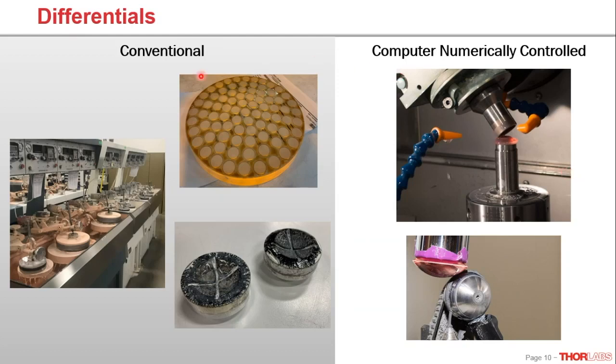And just a quick look at some of the images we have here. On this top portion, we're illustrating a variety of plano parts loaded onto a common block. By loading them onto here, as mentioned, it allows us to batch a large quantity of pieces. It also allows for a common or more common workpiece size for loading into our equipment, as you see here. This also allows us to maintain more consistency in a lot of the dimensions across the variety of parts too.